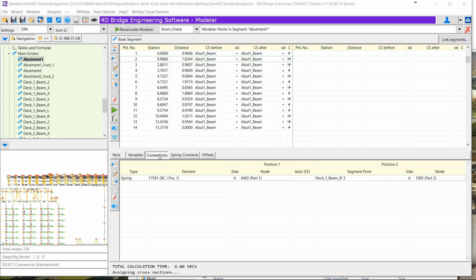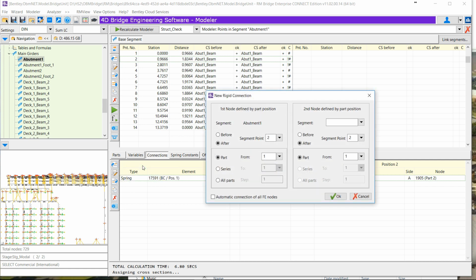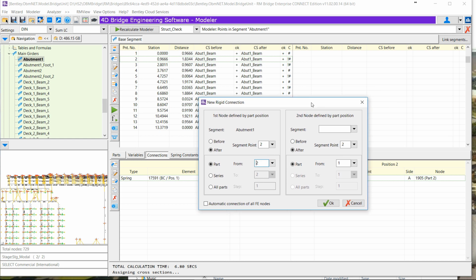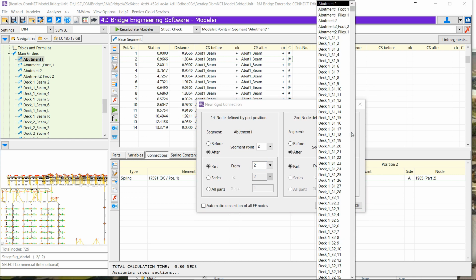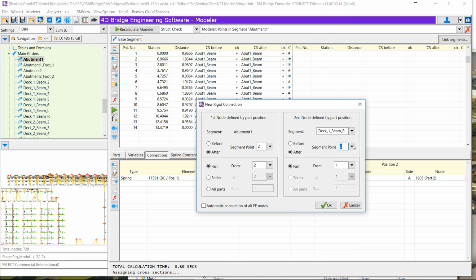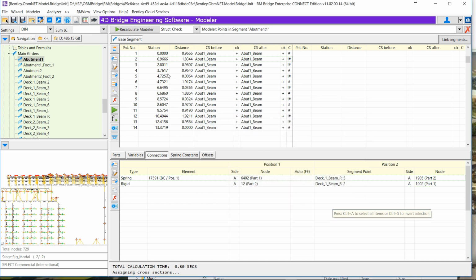And to make the connection with the beam, what we will say is that for each end of beam, we have a rigid connection between the node of the diaphragm and the end node of the beam, so that the diaphragm and the beams are rigidly connected. A rigid connection just puts only one node from which the beam starts, and this node is also part of the diaphragm beam. So this is a rigid connection, exactly what we have in our grillage model, for example. So I indicate for each beam what is the node I have to reattach.